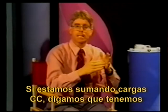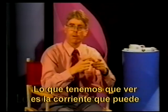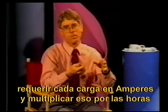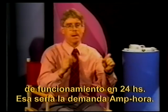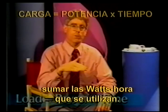If we're adding up DC loads, let's say we have DC lighting or some DC appliances, you want to look at the current that each load might require in amps and multiply that times the hours of operation in 24 hours. That would be your amp hour demand. For AC loads, it's slightly different. We want to add up the watt hours that are used.